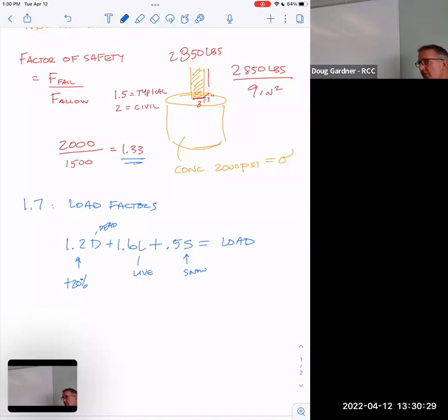Which again kind of annoyed me. They have this 1/2 inch bolt that sticks up and you have to have one every 4 feet. Well, you can appreciate that's a calculation some nerd like one of us made. Why is it every 4 feet? One out every 3, one out every 6, what distance is actually necessary there? But these bolts are 1/2 inch in diameter. And again, can you picture shear there? Because if the house is vibrating around, does it make sense they could shear that bolt off? So where did a 1/2 inch come from? Well, the stuff we're studying right now.